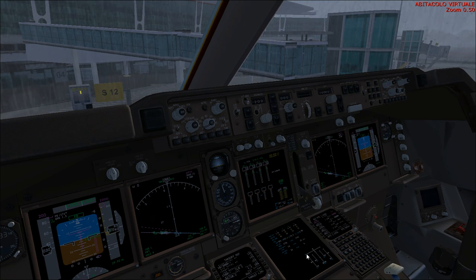Status display must be selected. We have selected the status display, and the AFIS control panel must be set. AFIS control panel, we have to select the minimums. We will leave them in radio. Actually, you should set on barrow and select the barrow altitude for the departure. Usually is the safe altitude. We can leave it at 500 feet, or we can usually increase or decrease depending on the situation.